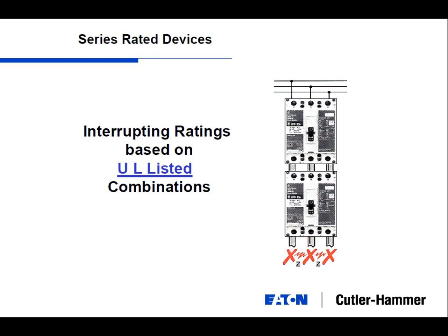If you think about an overload condition where you're just plugged in, or a very minor fault, there's a good chance your feeder breaker is going to trip first and your main later, or only in a high fault condition, a major fault, may the main trip first. So it's a little bit more reliable in that you've got a greater chance that your branch is going to trip, keeping the rest online and power going through it.